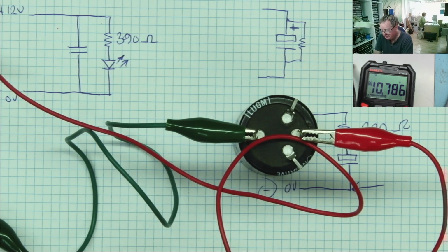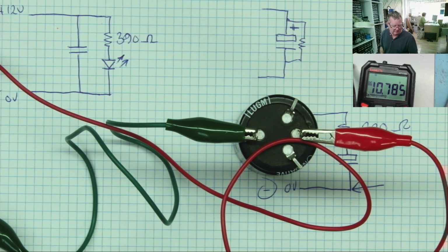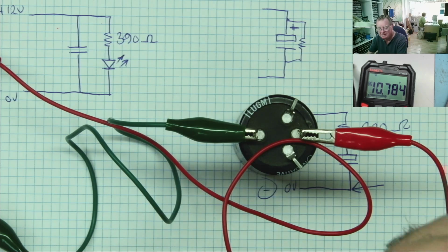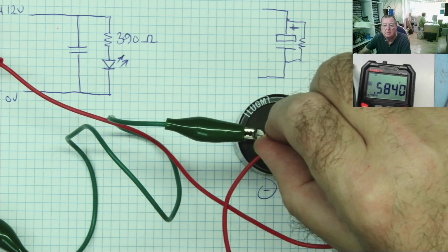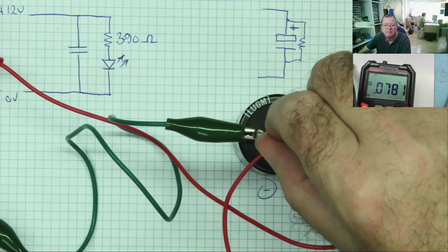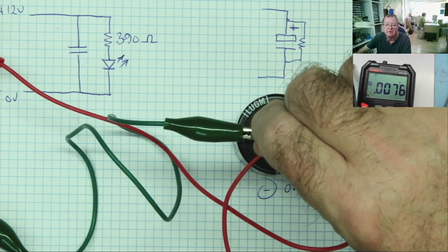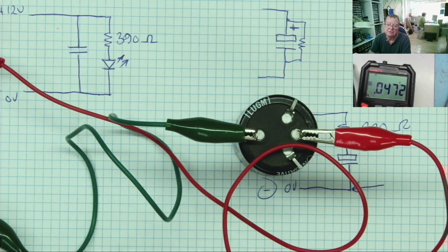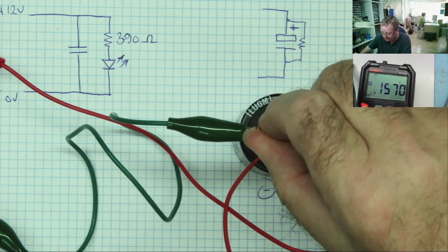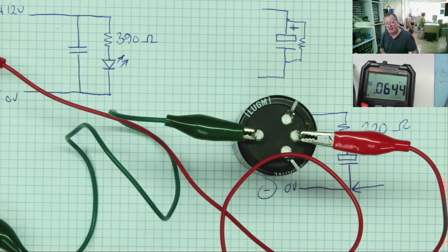There's my multimeter. You see this capacitor's got 10 volts in already. That's been sitting in my cupboard for quite a long time. We need to get rid of that. Let's use our 22 ohm resistor, a low value resistor. That should prove to you that capacitors can hold a voltage for a long time, because this was last used a couple of weeks ago on the live stream. Okay. I think we've pretty much got rid of that. You'll see the bounce back, of course. Okay, that's fairly well discharged.